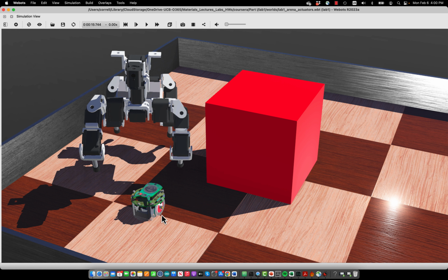And this is also the case of the e-puck. The controller on the microcontroller of the e-puck will generate the appropriate pattern for driving the stepper motors at a desired speed, and at the same time keep track of where the stepper motor is, allowing you to control the position of the wheel.